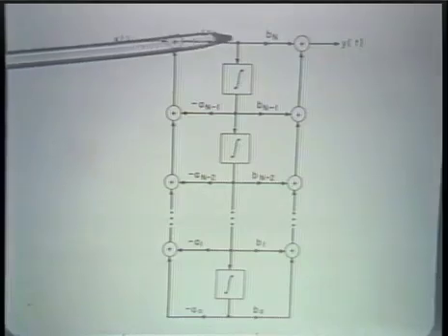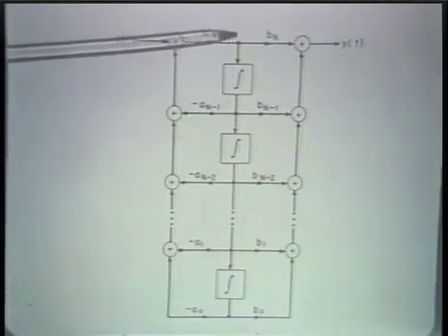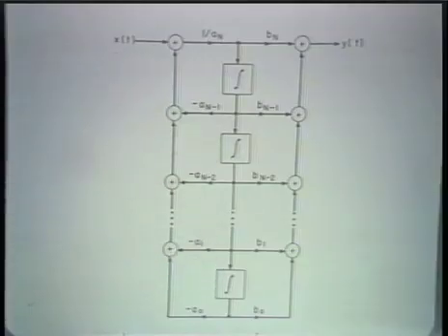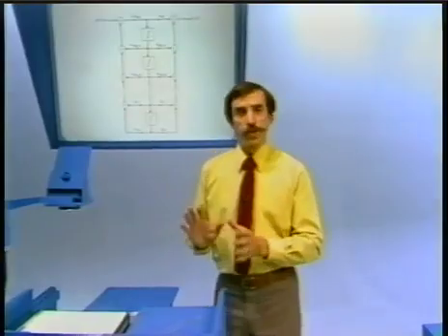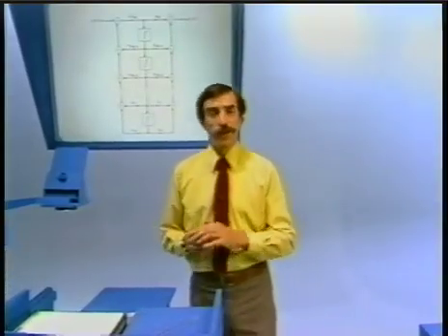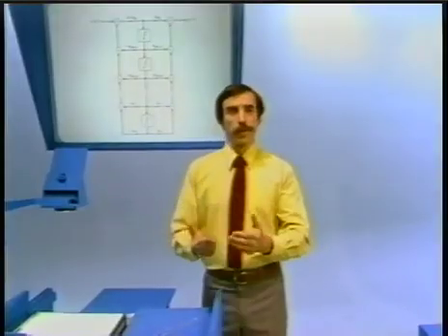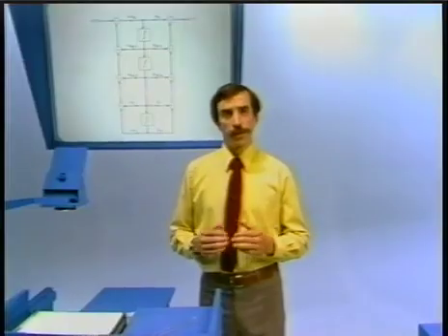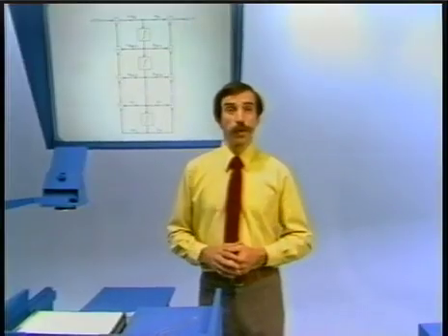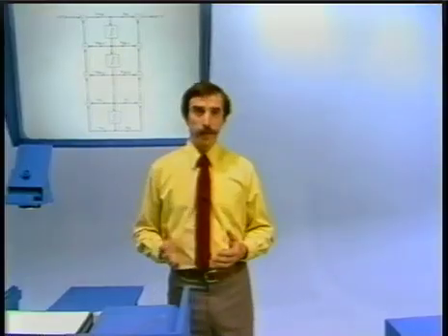So we have now just a single chain of integrators instead of the two sets of integrators. So we've seen that the situation is very similar here as it was in the case of the difference equation. Again, why do we want to cut the number of integrators in half? Well, one reason is that integrators in effect represent hardware, and if we have half as many integrators, then we're using half as much hardware.